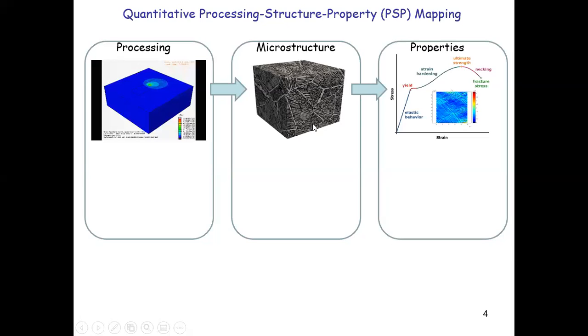Everything is going to be homogeneous large alpha grains. But when you heat it up and cool it down, these beta grains begin to grow as a solid transformation in the material system. So that's going to change the microstructure, right? So the whole material after you make it into a particular shape, the mechanical performance you measure will be different than the pre-alloyed powder because they have a different microstructure.